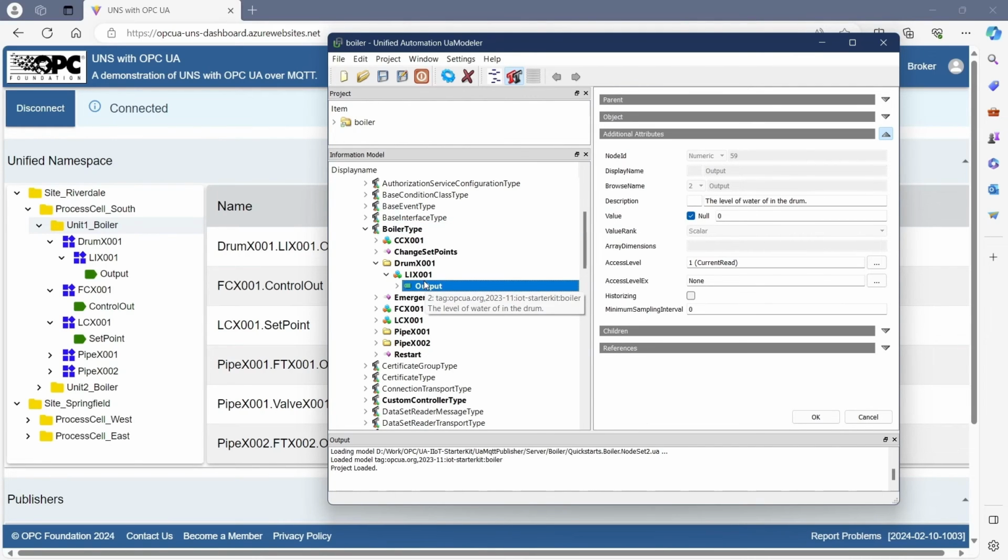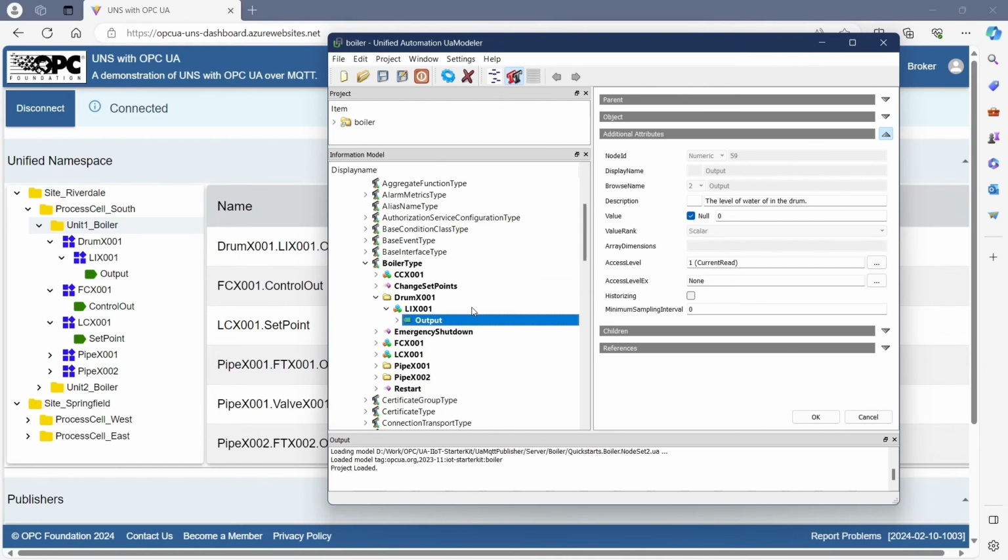The need to restrict access to some data is where the ability to specify site-specific topics becomes quite useful. For example, let's say a machine installed in a factory provided maintenance information that the machine vendor needed to access. Yet the same vendor should not be given access to data for process information belonging to the factory operator. In OPC UA, a single publisher can publish two different views of the device to two different topics to resolve these kinds of conflicts.